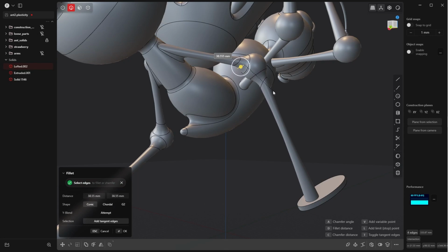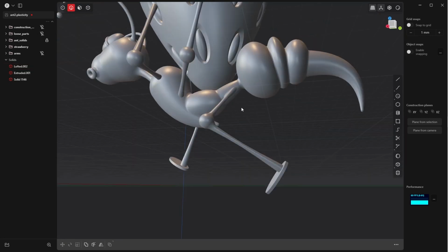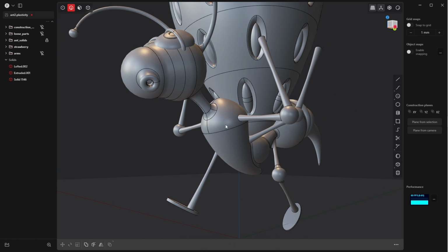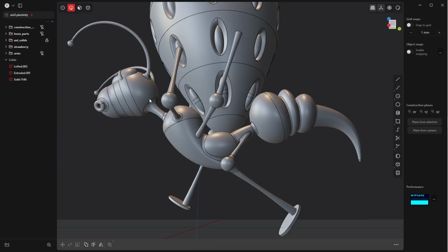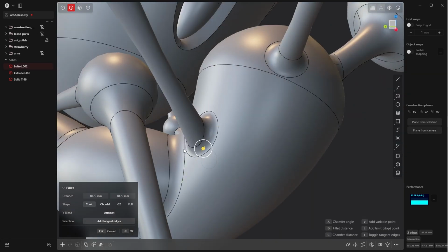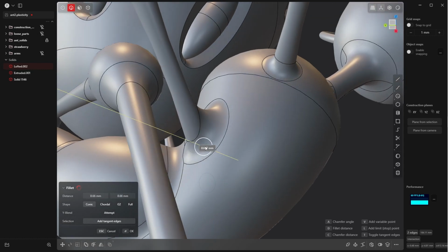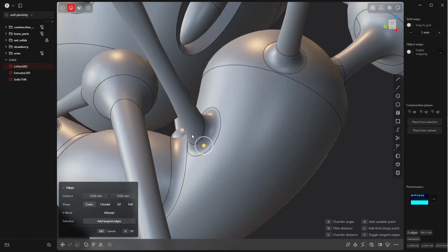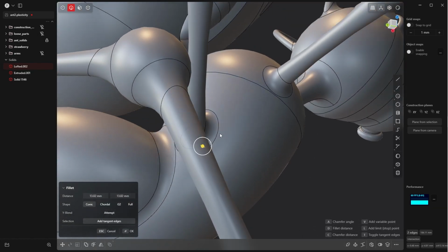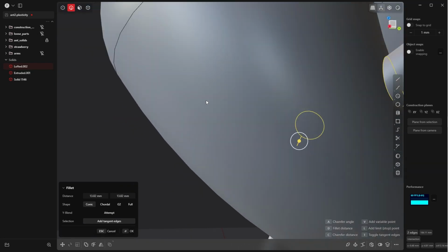Make a quite big fillet. Of course, time lapse. That's what I was talking about. If we make the fillet big, which we can, then we get weird intersections. This type of topology, you can go back and correct it. I don't want to spend time correcting it. I will rather leave it like this, so we don't have a situation where we have to make corrections afterwards.